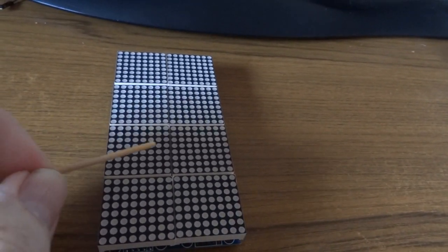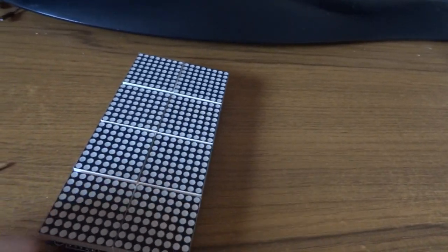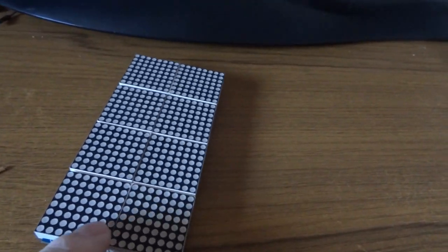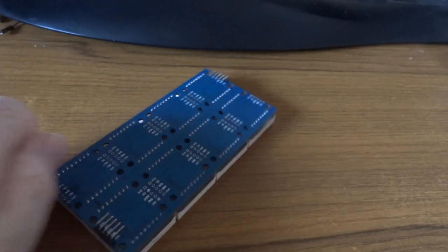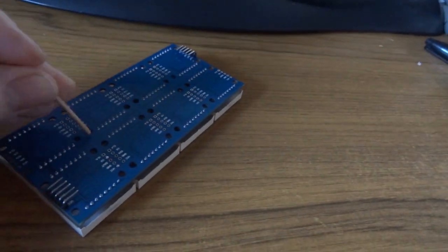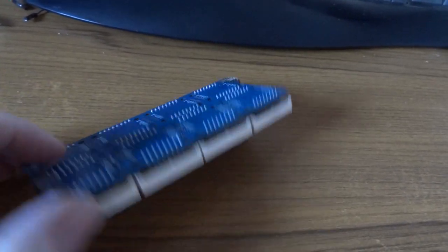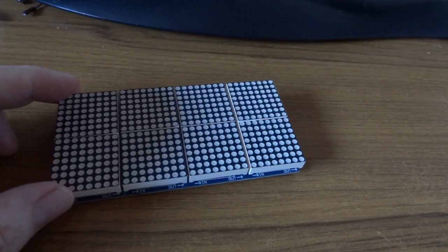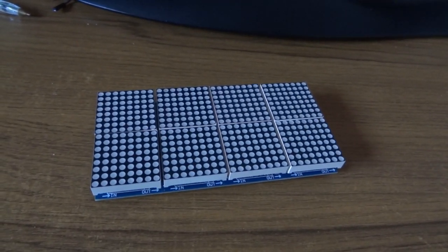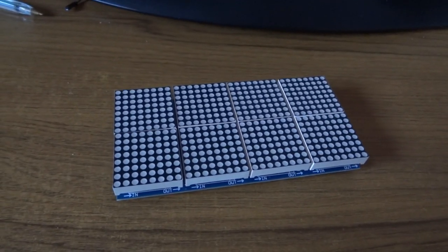Incidentally, this is a cut-off cocktail stick, and it's useful once you've got a number of these blocks assembled together and you want to remove one of the display LED things, because they're just pushed into chip sockets. This little cocktail stick, you can prod through the holes and get them out without bending the pins, whereas just levering them from the one edge, you tend to bend the pins getting them out. Okay, enough of that, and I'll move on to showing you how I connected them up in a frame to make the whole display.